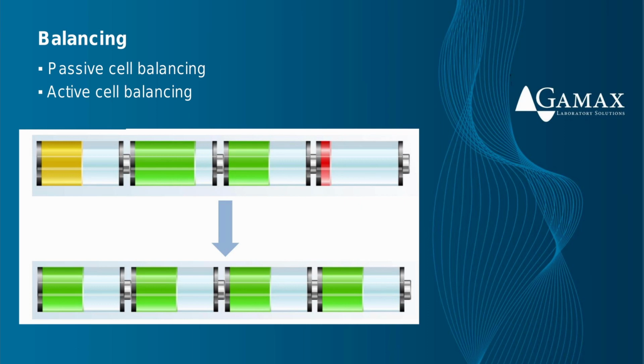Cell balancing is another important task of the BMS. Cycling a battery pack eventually causes individual cells to become out of balance, which typically results from different Coulombic efficiency across the cells. It is undesirable because it limits the energy that enters or exits the battery pack, since the weakest cell limits the amount of charge that can be drawn from the entire system, and the strongest cell limits the amount to be discharged from the system.